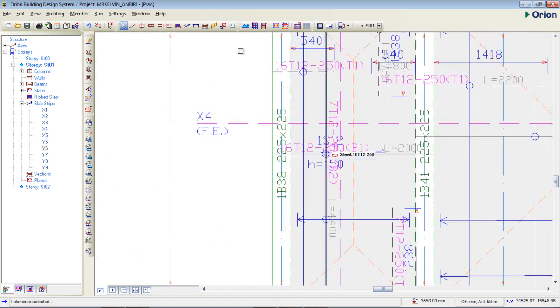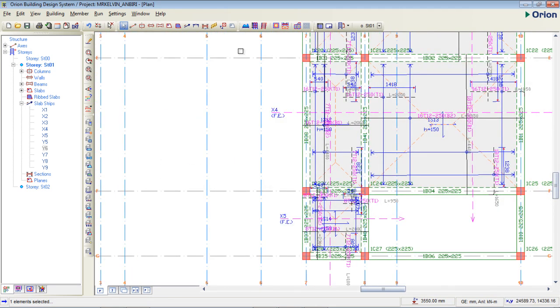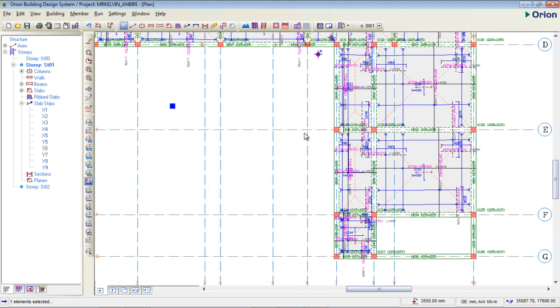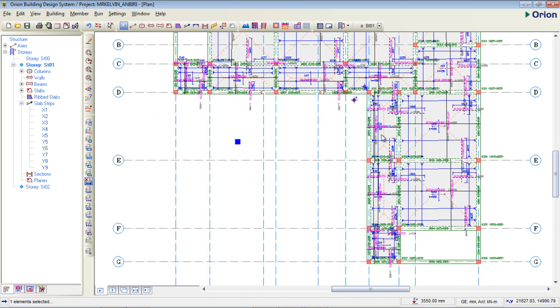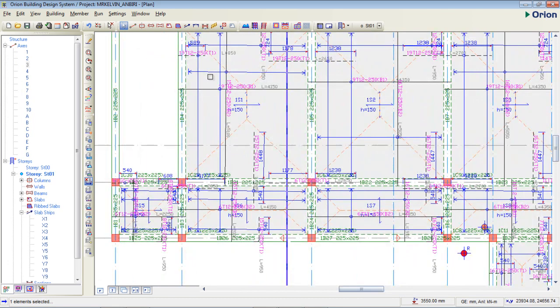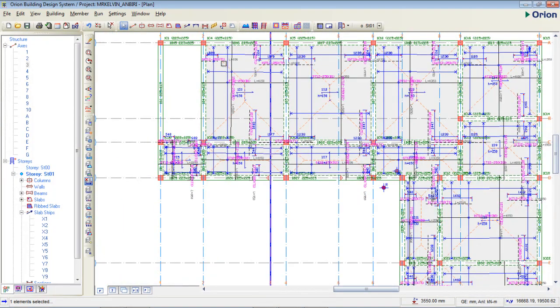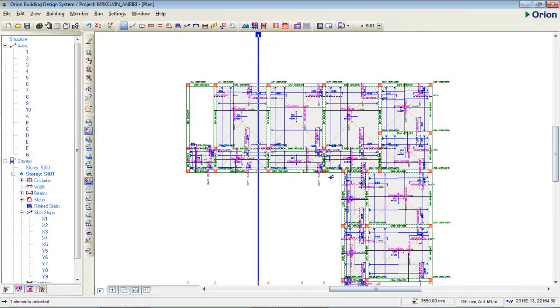Let me click on this. By left clicking, then I'll right click, then this flyer pops up. Then I'm going to go to Arrange All Steel Bars. Then I'm going to go to this arrow that comes up. I'm going to go to update steel. Then I'm going to click on update steel. That's pretty smart. Now all rebars have been created at once automatically, and it's very smart.